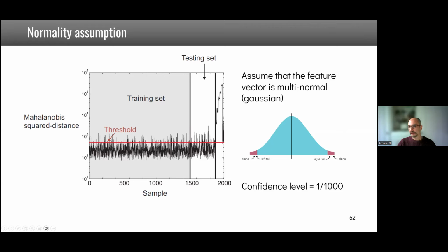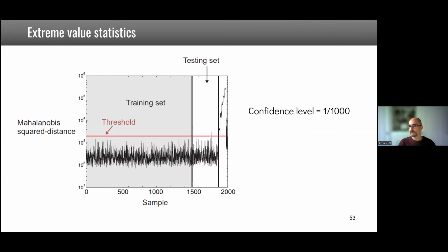And so you will not have a good representation of the tail. There is no chance, okay? That's always a problem, as using the normality assumption for extreme statistics is nonsense. It never works, okay? So the way to do that is to use so-called extreme value statistics.